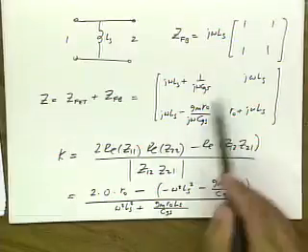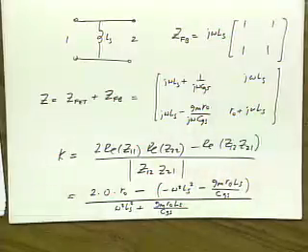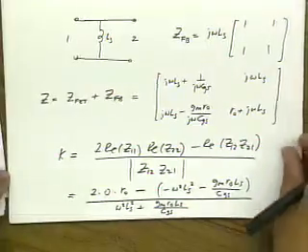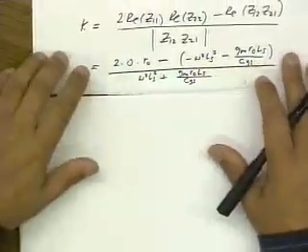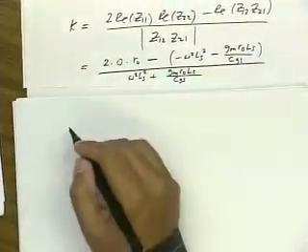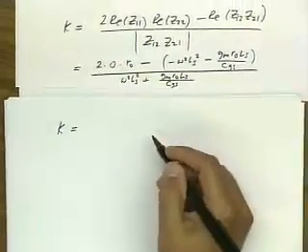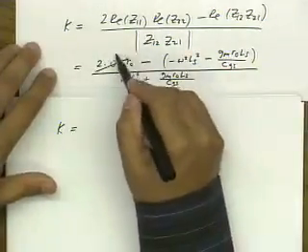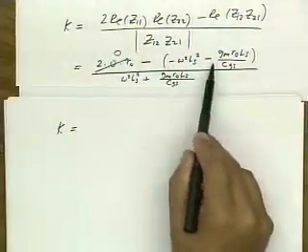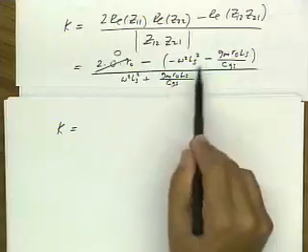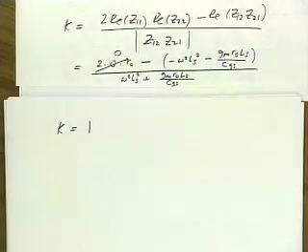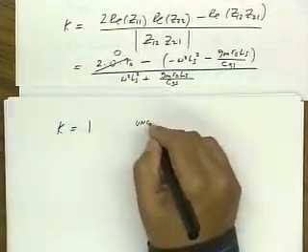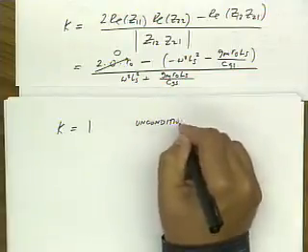Okay, so it's just the magnitude of this product. Okay? So that's our K factor. And what we'd like to see is under what conditions is K greater than 1? Well, take a look. Now this term is all 0 here, and this term becomes plus, and so now we see this ratio is exactly equal to 1. So this is unconditionally stable.